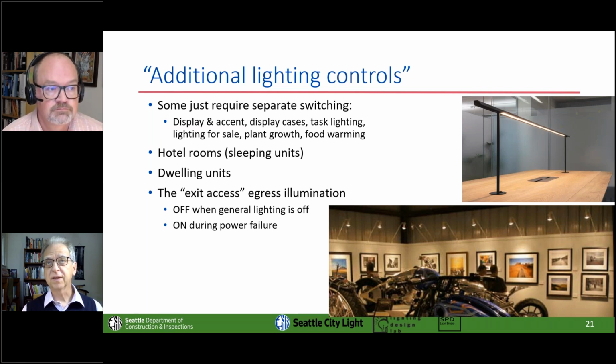It's something that I've noticed that 95% of projects probably do not have a professional lighting designer involved, and those are the projects that often get occupancy sensors that are really inappropriate for the space. And there's all different kinds, and sometimes you use multiples of them together to make sure you've got complete coverage. And if you've got toilet stall partitions or open office partitions or something like that, you have to accommodate all those things. So that's where having a pro involved really helps.